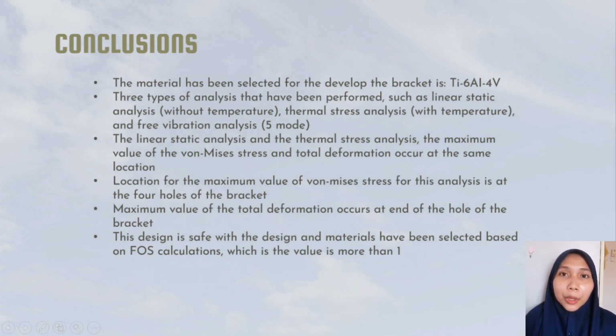Based on the results of the linear static analysis and thermal stress analysis, the maximum value of 1st principal stress and total deformation both happen in the same location. In these two analyses, the maximum value of 1st principal stress is at the 4 holes of the bracket, and the maximum value of total deformation is at the end of the bracket holes where the load is applied.